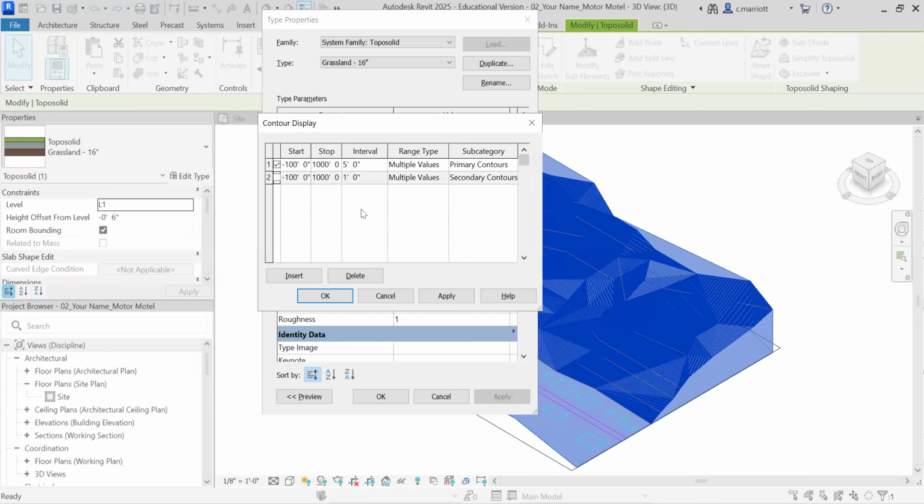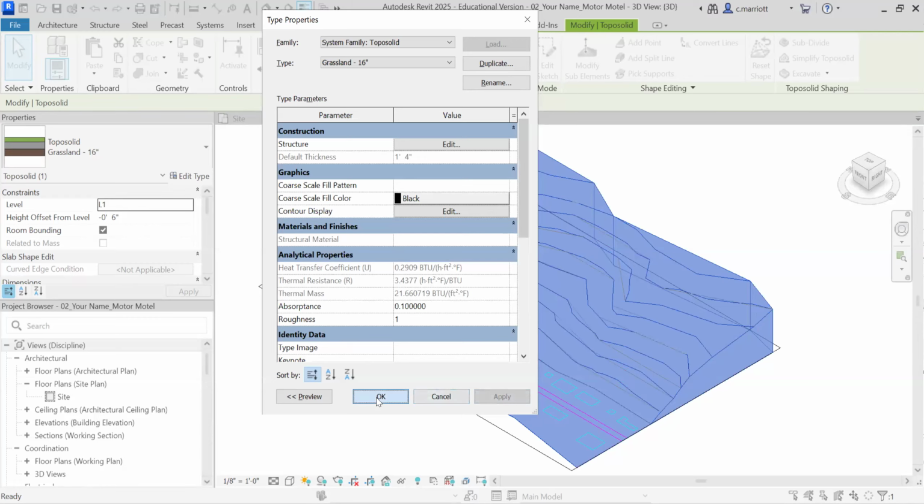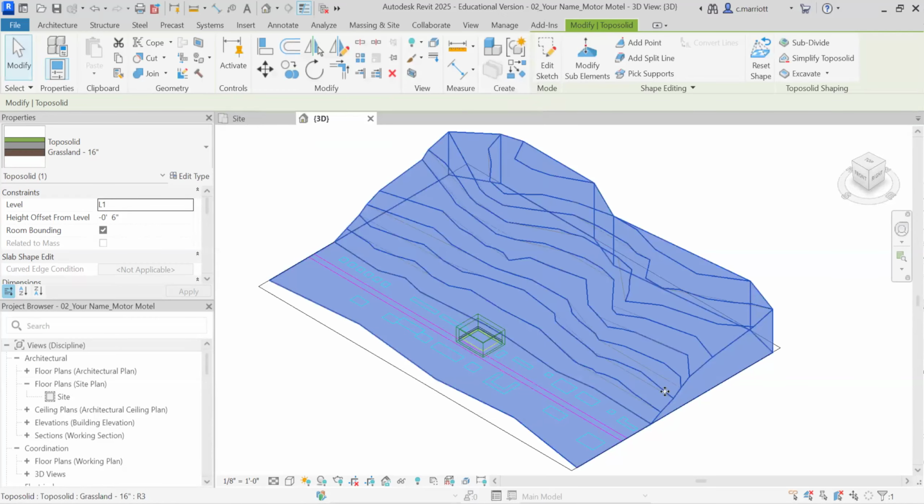We're going to turn off the small one, and we're going to change the interval to 50 feet. This is a very steep slope, and the contours that were drawn in AutoCAD are set every 50 feet. So these gray lines that you see. All right, now we're going to hit apply and OK. Let's just take a look. Okay, so that is what's happened. We've turned off those other contours, the ones at lesser increments, and now we're just left with these 50-foot contour lines.